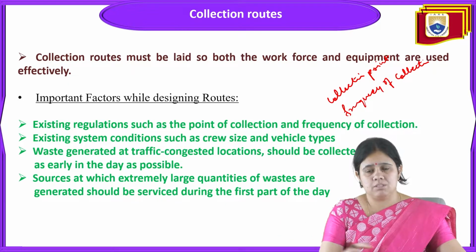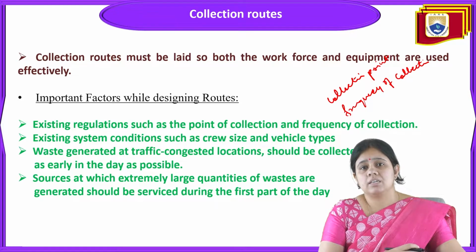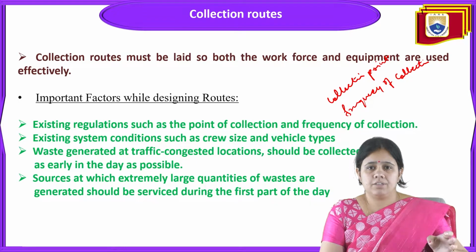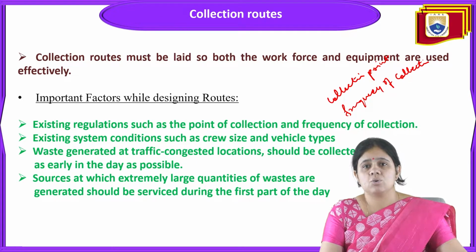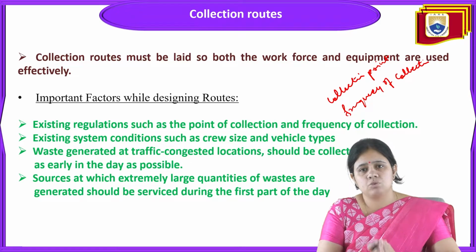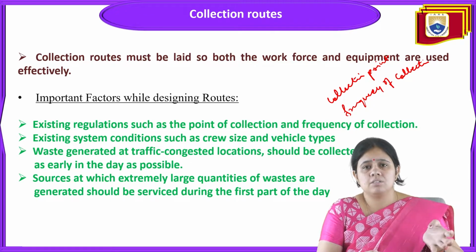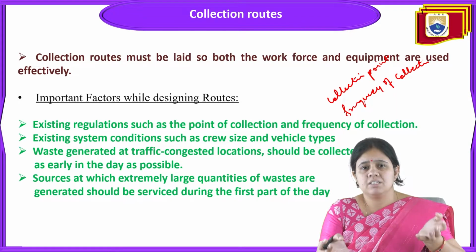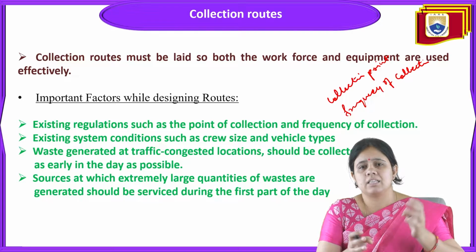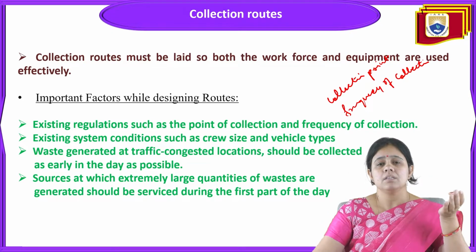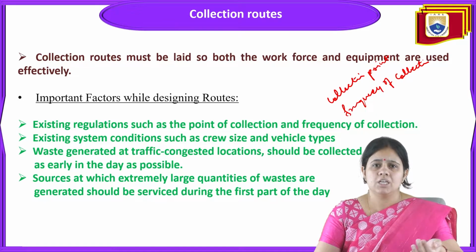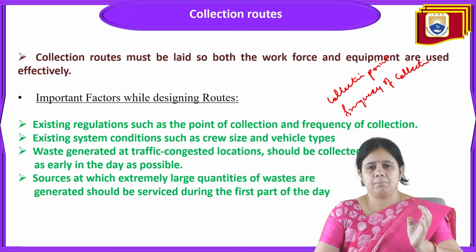What is the frequency, meaning how much waste, what is the general trend of garbage collection in that particular area. If there is a larger amount of waste, then the vehicle size should be bigger, and the crew members, the persons doing the work, should also be more. If very little waste is generated and collection is also less, like once in a week, then the crew should also be smaller. These are the things to keep in mind while designing the route